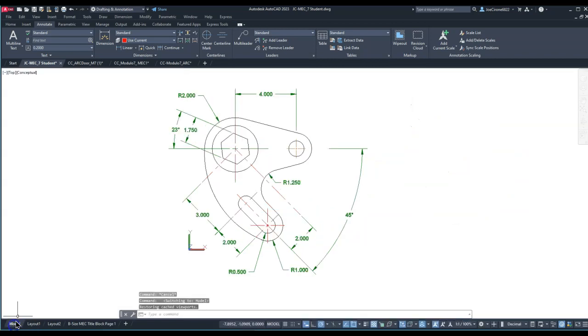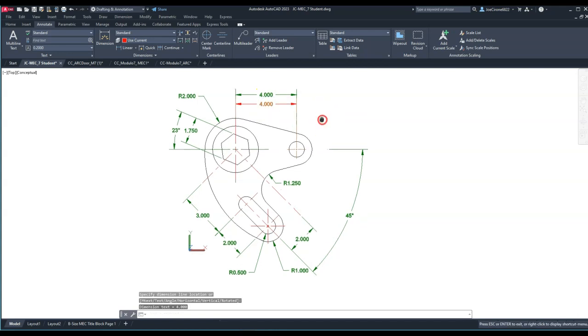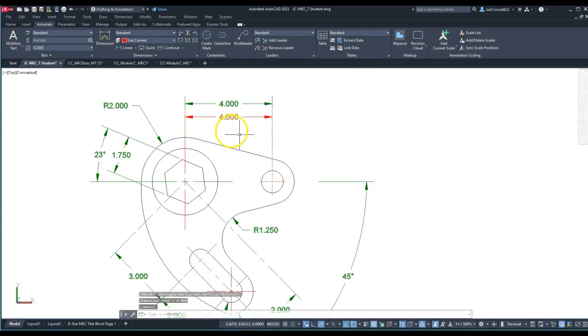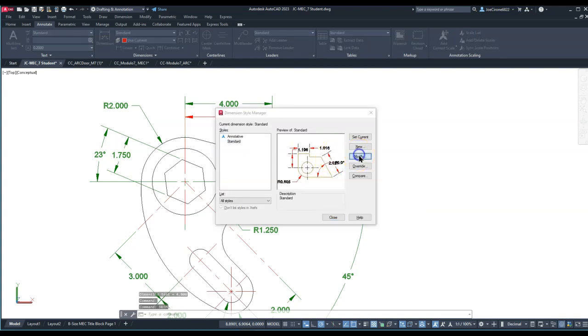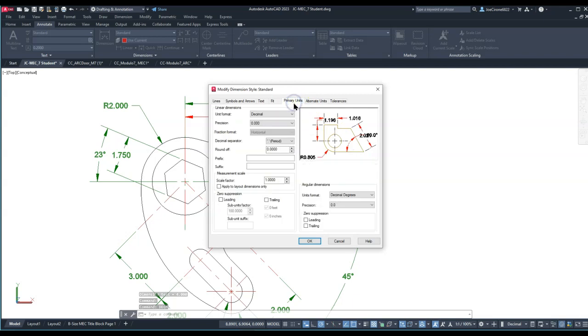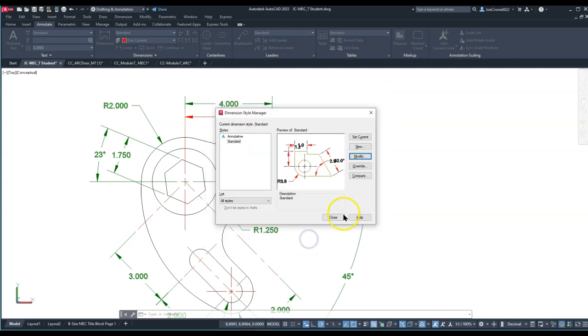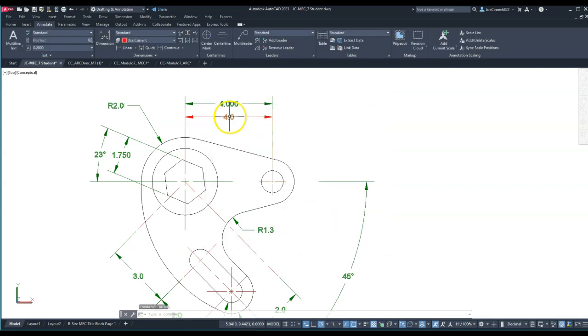And so if I were to go to Model Space and put another 1-inch dimension on that, another linear dimension. And so that's my dimension for that linear dimension. And then we can also update things like our units, primary units. And so number of decimal places is controlled here. If I have 1 decimal place of accuracy and say OK, close that, you'll notice that it dials it down.